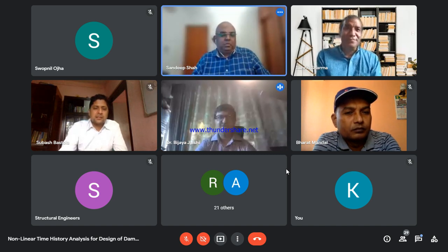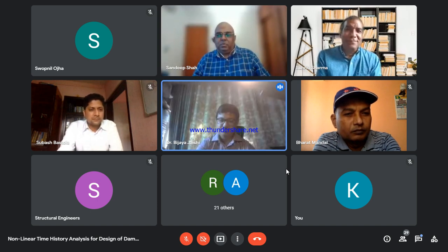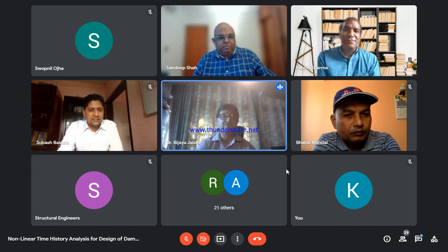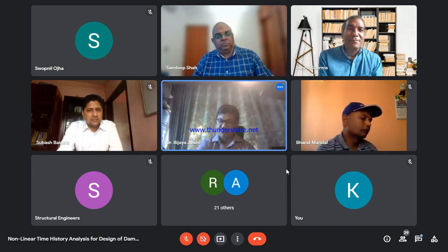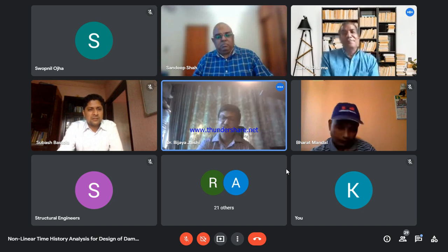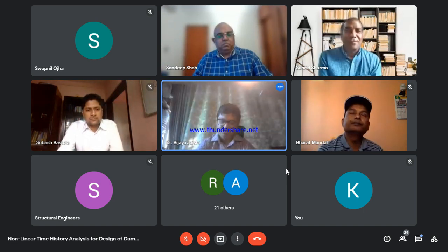Okay. Thank you, Sandeep. So at last, in a nutshell, the building is required to have a performance objective. Every building. So we should control the structural roof, maybe roof displacement, inter-story drift, reduce base shear. So the damper is used mostly for this performance objective.